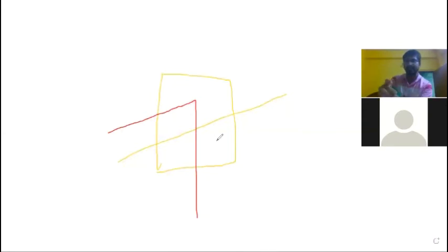And if we see perpendicular to the cutting plane, suppose this is your cutting plane. For this cylinder, if you see from the top, you see a circle. But if we see perpendicular to the cutting plane, then this will be the ellipse. So this view is called the true sectional view.